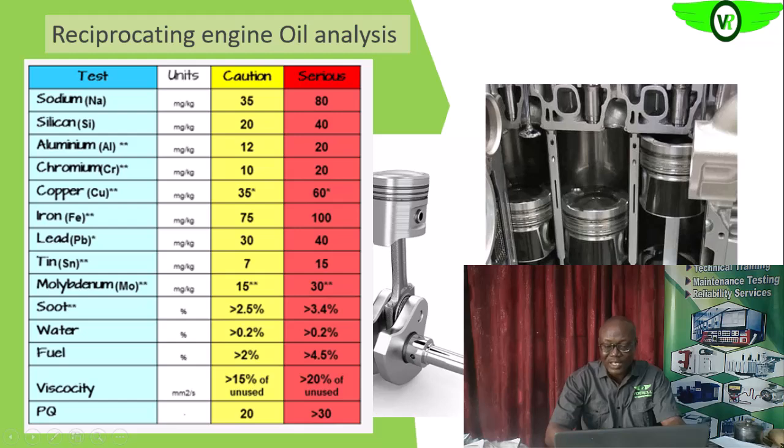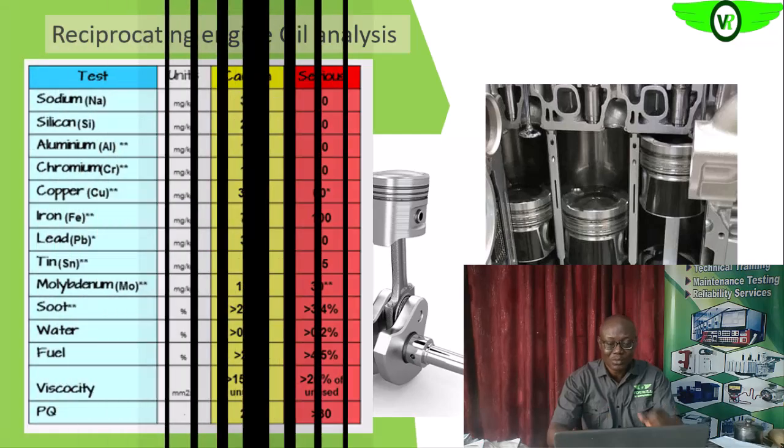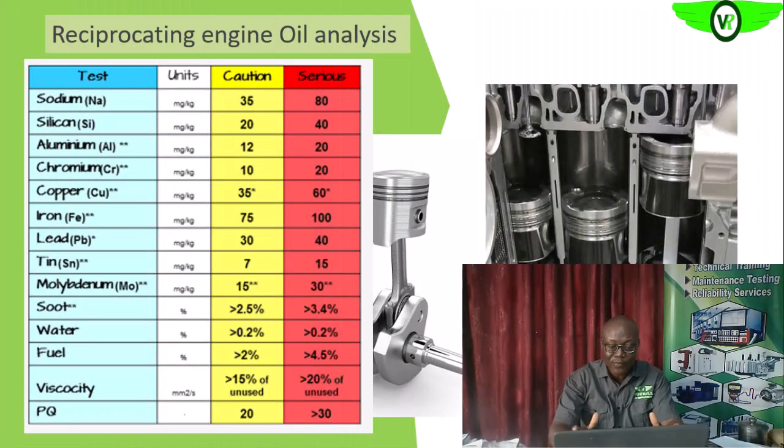The movement of the crankshaft will contribute. The movement of all of these valves, the camshaft, the cam followers, even the timing gears and other gears behind, all of them will contribute to the overall vibration. So trying to identify each of these forcing functions will not be too easy.